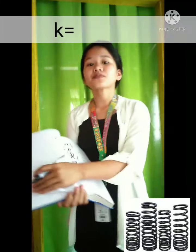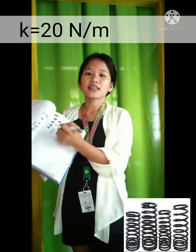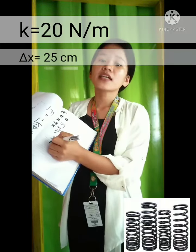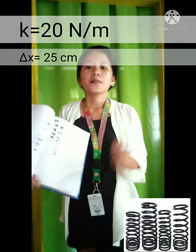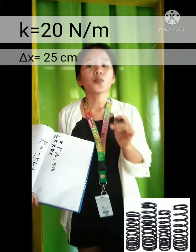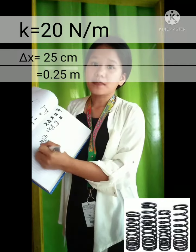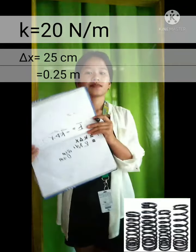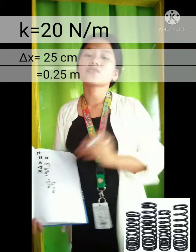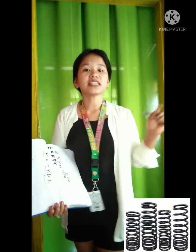So k is 20 N/m, and delta x is 25 centimeters, which converted to meters becomes 0.25 meter. Now we plug these values into the Hooke's law formula. Since we're looking for the force required to pull the spring apart, we don't need the minus sign.